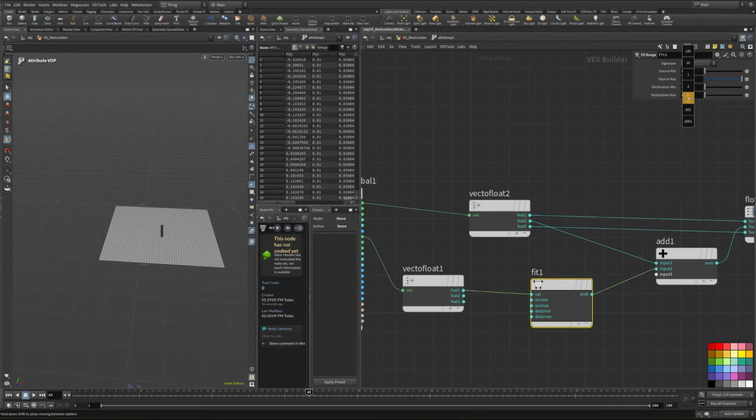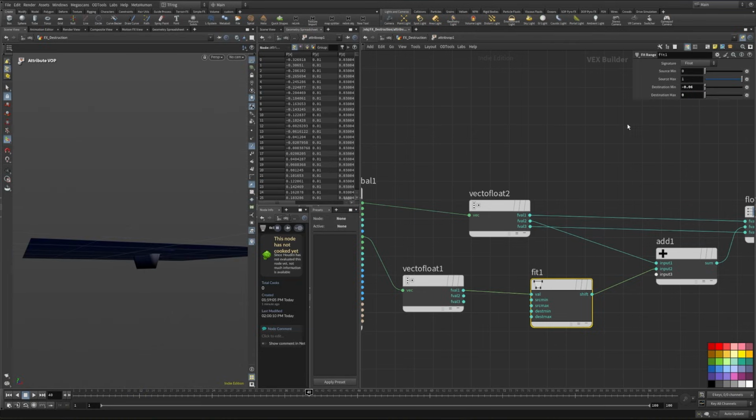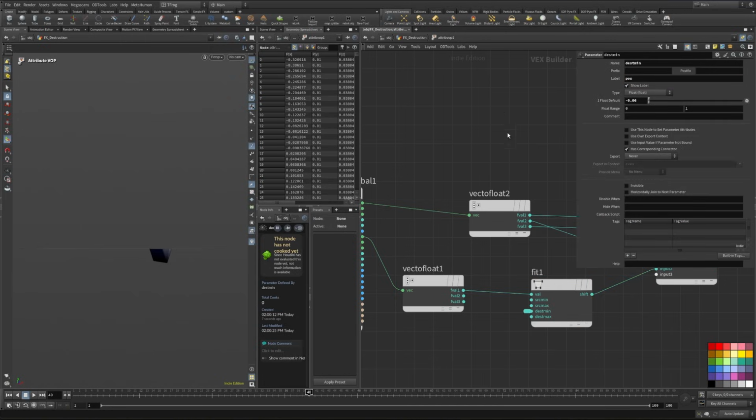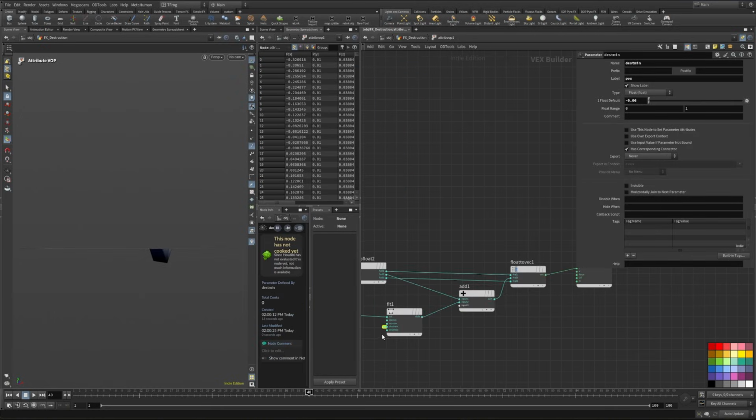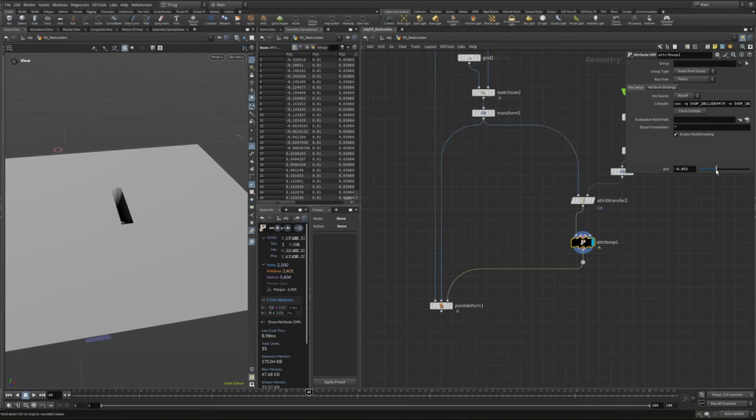But this direction needs to get dragged down now. And you can see we can control this part here only with this scalar. So we can promote it over here and call it position. Now let's move up. Maybe I'm getting back in so I can change the float rate to minus 0.3 and 0.3. And we can select the attribute VOP here and control it now.